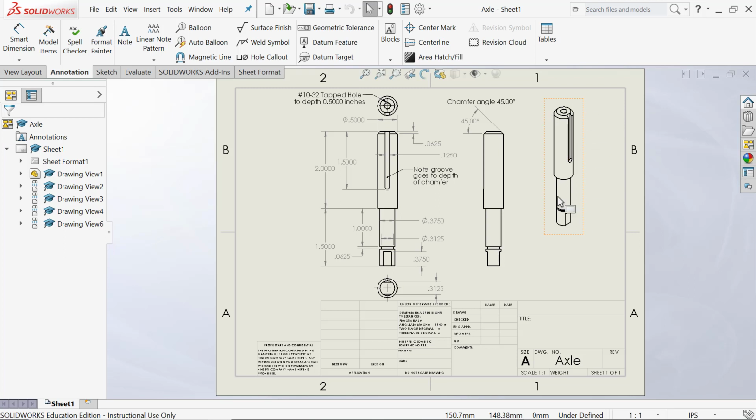If everybody will look up from your papers, this is a cylindrical object. It has a larger cylinder coming upward from this transition between the two. That larger cylinder has what's called a chamfer applied to the top. It's much like a fillet, except instead of being rounded over, it's cut at an angle, 45 degrees, and has a dimension, 0.0625, to tell you how far to apply it down the surface. So that's a chamfer, C-H-A-M-F-E-R, as indicated there.